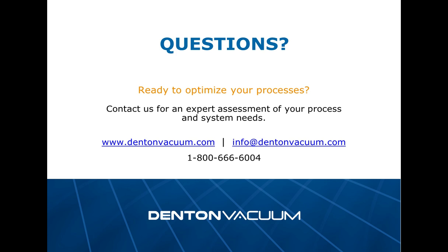So MBE is typically used similar to MOVPE or MOCVD for active layer deposition. You can get very high quality materials. It is somewhat of a slower technology, but again, if you need very sophisticated active layer stacks, MBE would typically go into that slot in the manufacturing process.